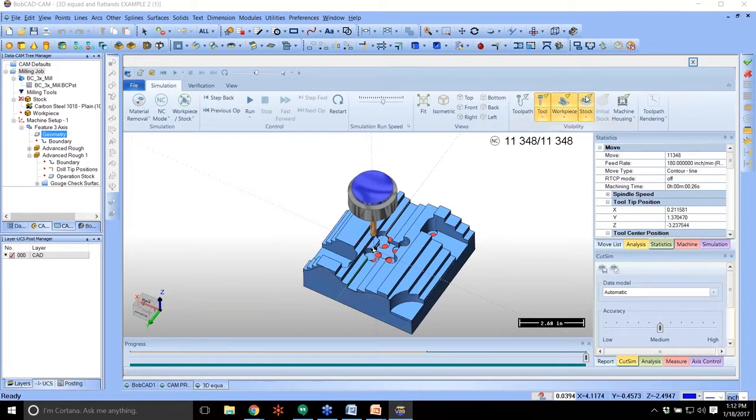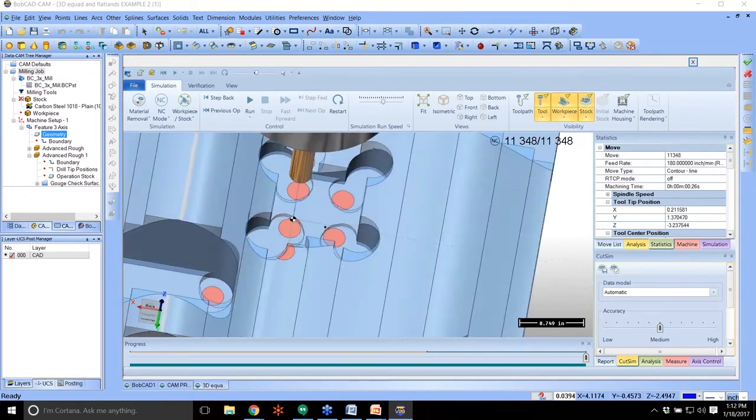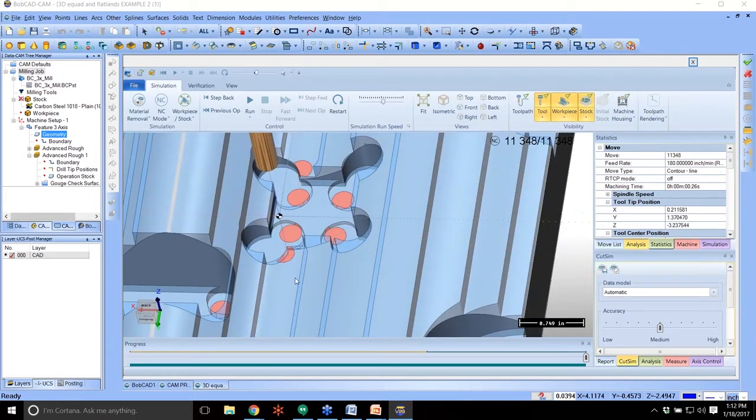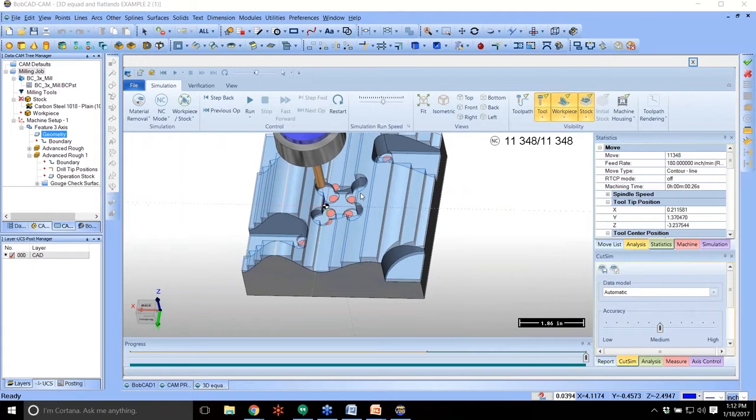Because if we turn on the workpiece, just so you guys can see, this might come up where you have noticed it. If you look, we still have material in that area. We're not actually colliding or cutting through. We still have material to remove with maybe a Flatlands or something like that, which we're going to cover as well. Now, as you can see, we handled the rest roughing. So that's how you decide if you're going to use a rest roughing. That's how you decide the style of roughing based on the part itself, okay?